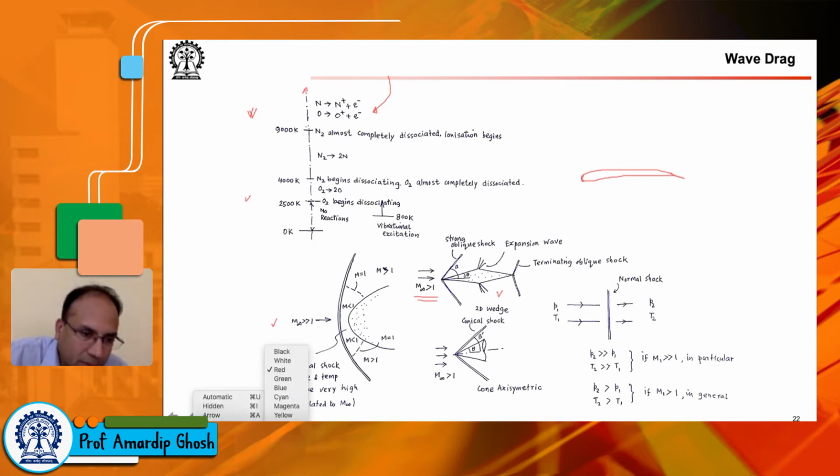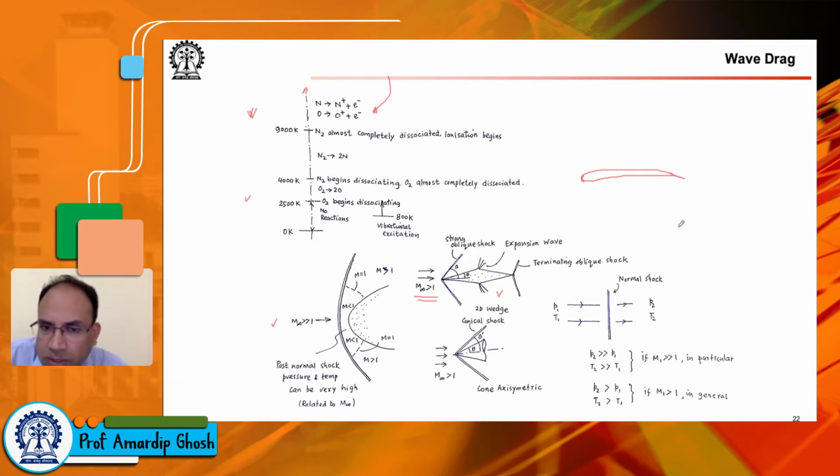So this is also because we are talking about wave drag. So this is wave drag, keep in mind. This wave drag happens due to shock waves. Now, shock waves typically are associated with supersonic flow fields, but supersonic flow fields can happen even in subsonic flight because of local accelerations. Okay, keep that in mind. Whereas in supersonic vehicles, of course, your free stream Mach number is supersonic to begin with, and there what happens is as the flow deflects.